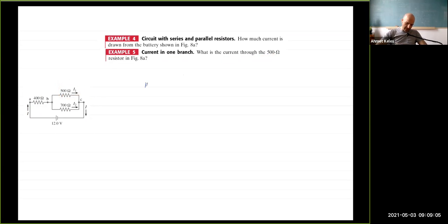So I can find R equivalent. First, I need to do this guy, starting from the innermost connection. And I know these are parallel connections. R is equal to what? If it's (1 over R1 plus 1 over R2) to the minus 1, this should be equal to ((R1 plus R2) divided by R1 R2) to the minus 1. So this is equal to R1 R2 divided by R1 plus R2. So let me just calculate this and put it in there: 291.6, 291, maybe that's good enough.